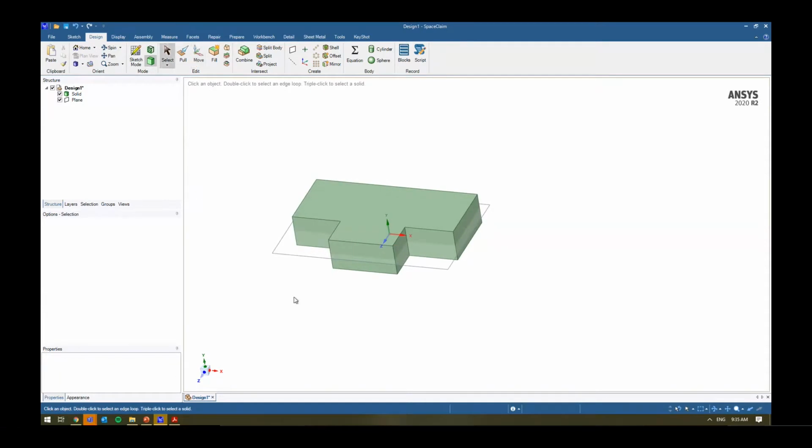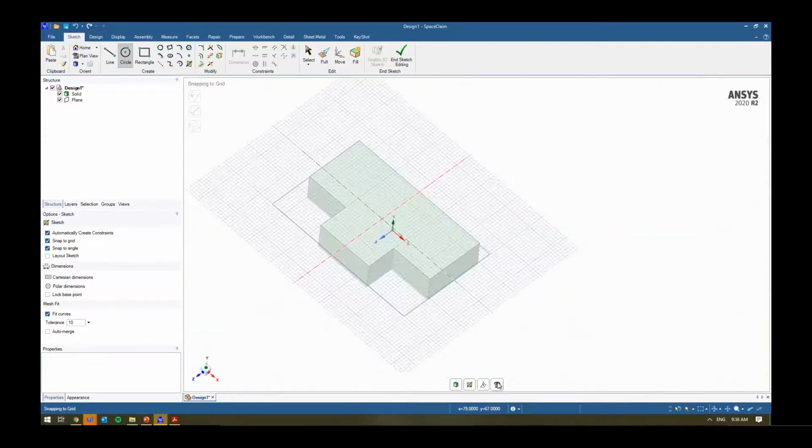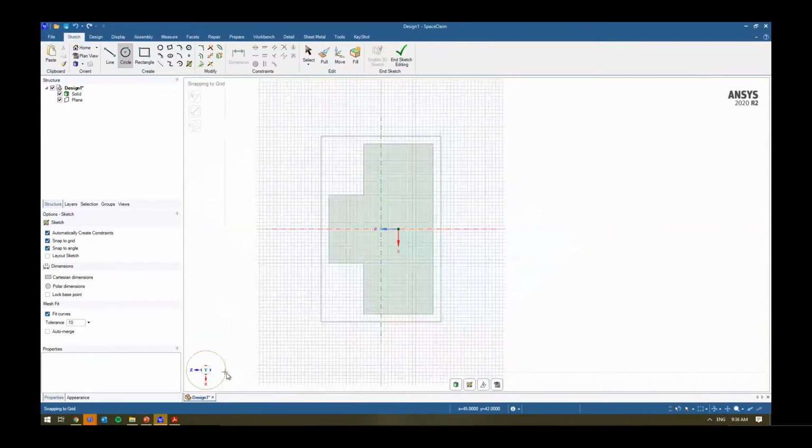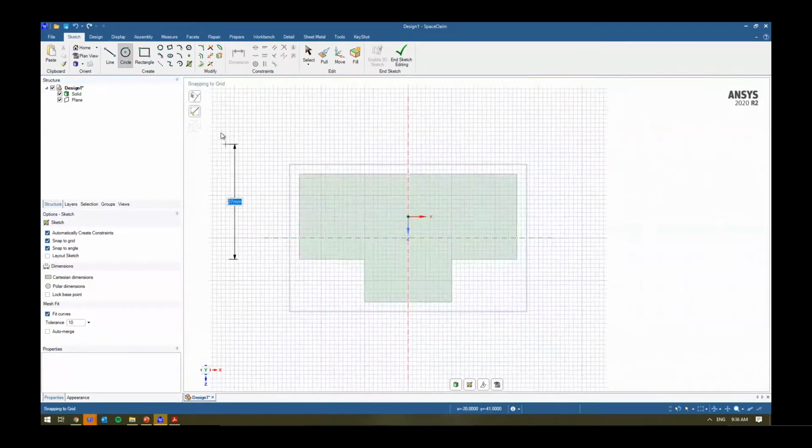All right, so let's continue creating this sketch. So after I've done this, what I'd like to do is create a sketch and create some holes and extract some surfaces as well. So again, we can go back to our sketching. I can select that and hit my circle button. At the bottom here, I've got some options. Plane view is V. So if I select that, it'll snap me in, and I can move it into however I want.